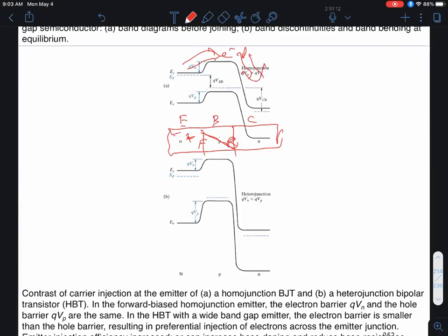Okay, so I'm increasing the supply of carriers, and therefore the effective leakage current of this reverse bias collector base junction. Okay, so that corresponds to my most important current component of electrons flowing out at the collector. Remember, of course, that the current vector actually points opposite to that, but just for the sake of clarity, I'll show the vectors in terms of the particle flow, the electron flow. Okay, so the electrons are flowing out this way, but of course the current is opposite to that. Okay, so this is the most important current component, because that will be my useful output current at the collector.